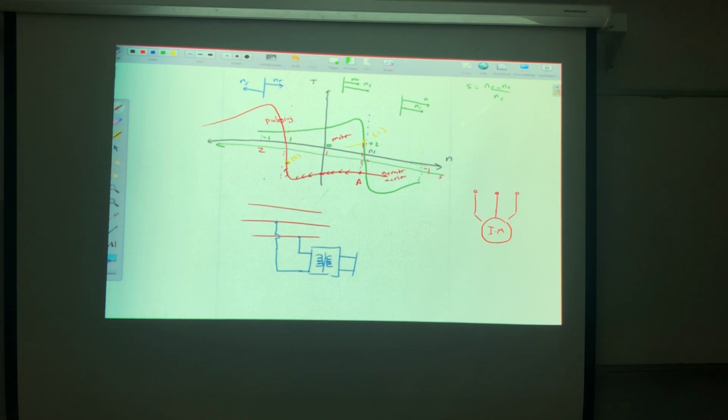After that, here I will use the uncontrolled rectifier. It can be controlled or uncontrolled, but assume that I'm living in heaven. So I will use an uncontrolled rectifier. Those will be connected to the terminals of the machine. Any two terminals. I don't need the three. Only two terminals are enough for me. This one is floating. Now the stator will generate stationary flux. Let's say this is a north and this is the south.